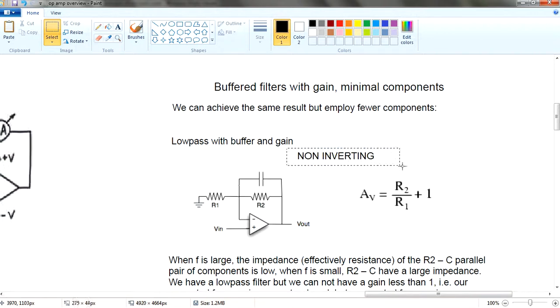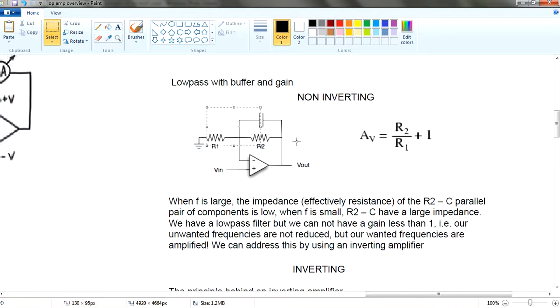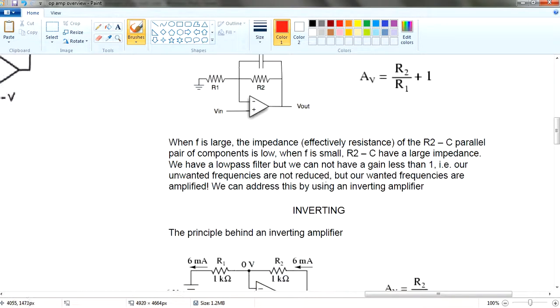This is also non-inverting. Okay, sure. So your Vin is also input into the non-inverting side. However, your feedback you can connect in this manner. Your capacitor is parallel to your resistor, for low pass. Alright, just stop here first.